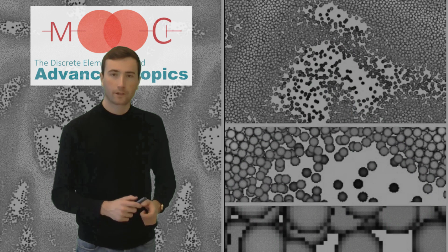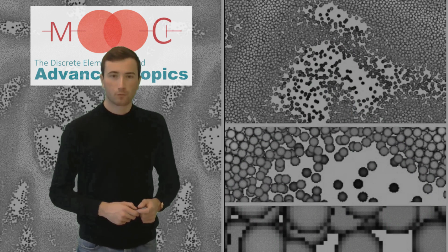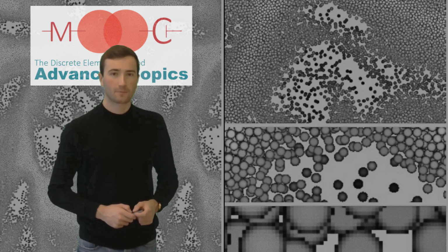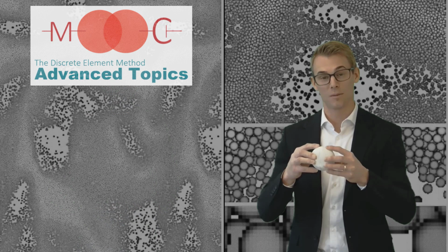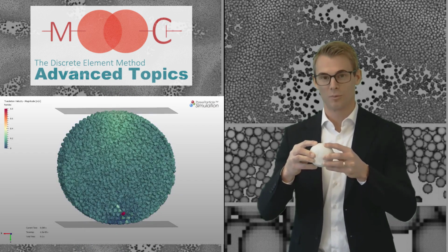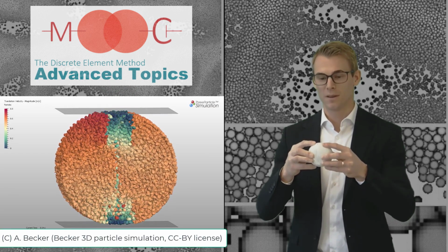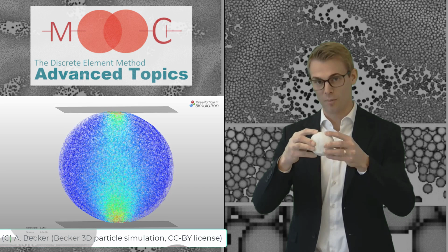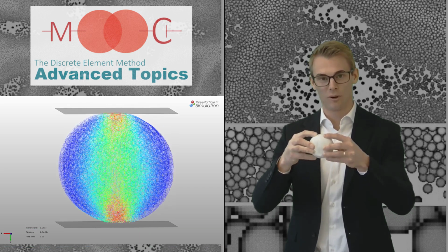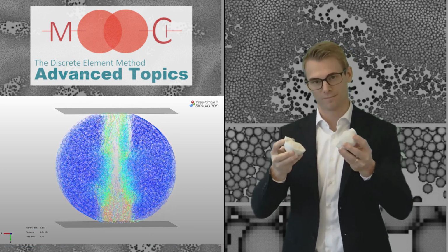Now, when it comes to this breakage you mentioned, how does this property contribute to the DEM simulations? For instance, a rock modeled as a bonded particle model is able to break into smaller pieces when subjected to a respective load, with the crack propagating naturally as local bonds exceed their stress limits.